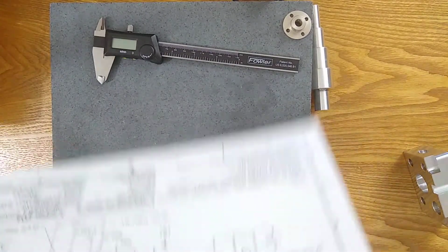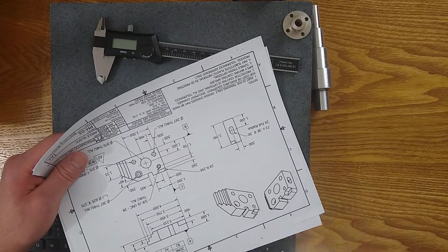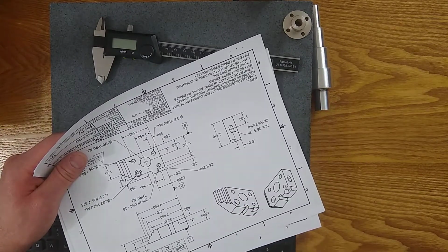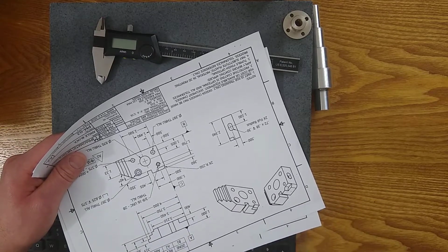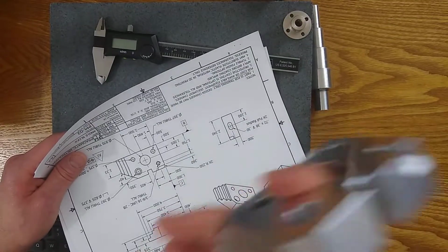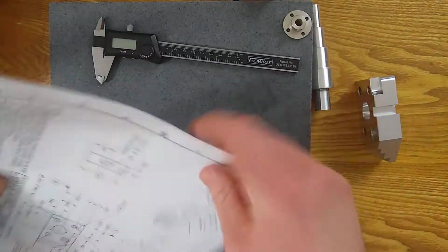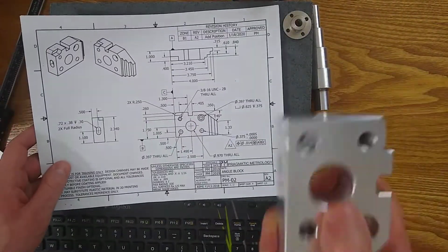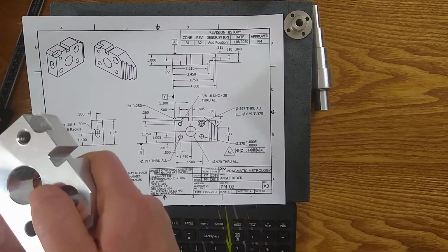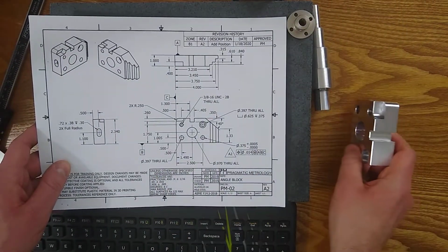Check the material. Material of parts is usually controlled. They want it to be a certain steel, certain aluminum, certain plastic. They all have important properties. And if you grab the wrong material, then you may have made the part correctly, but it's not going to be usable. Verifying the material usually means verifying the certifications that come with the material. So you won't necessarily be testing the material, but you'll want to verify that, yes, this material came from this lot, and this lot is certified by the supplier to be this specification of material.